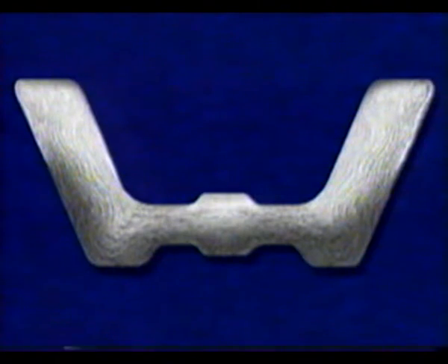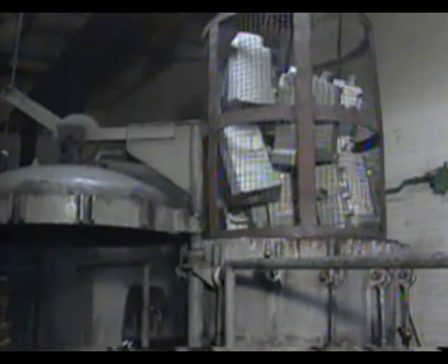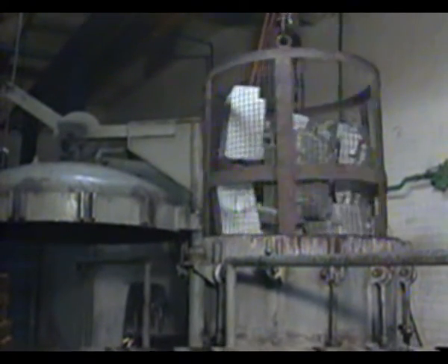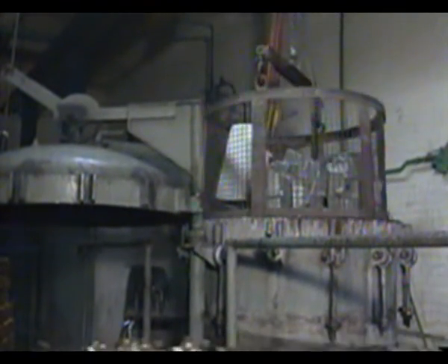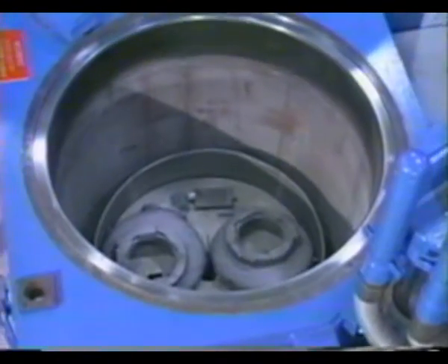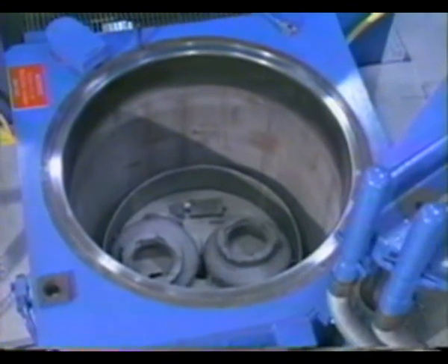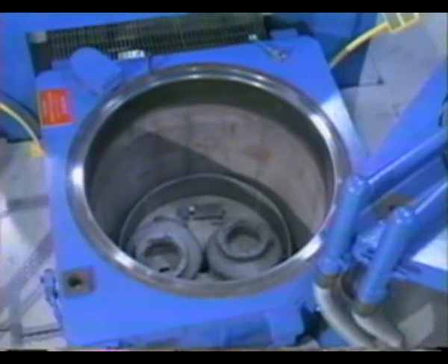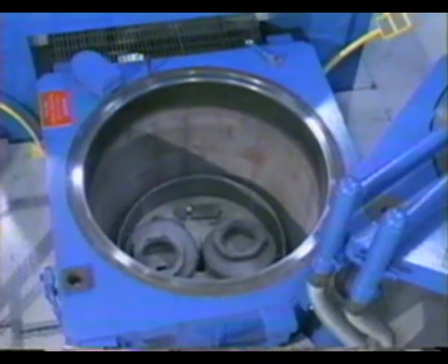Castings typically have an isotropic or uniform grain structure and properties, rather than the directional grain structure and properties of wrought metals. However, castings only approach the full or theoretical density of wrought metals. Surface porosity of castings can be eliminated by sealing with a resin or a metal. Internal porosity can be reduced by isostatic pressing, improving the casting's mechanical performance.